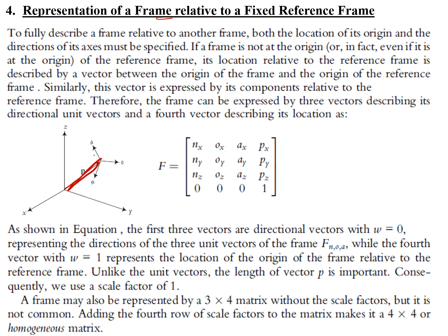So there is a distance between them. In the previous case, you have this frame, and it is only displaced. But here the origin is different, you have some distance, and that distance is p. So how to represent this? The same thing: nx, yx, these are rotation matrix components, but this should be px, how far this point is displaced from the x-axis, y-axis and z-axis.